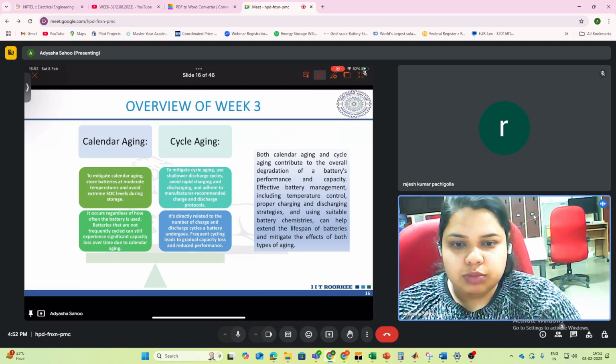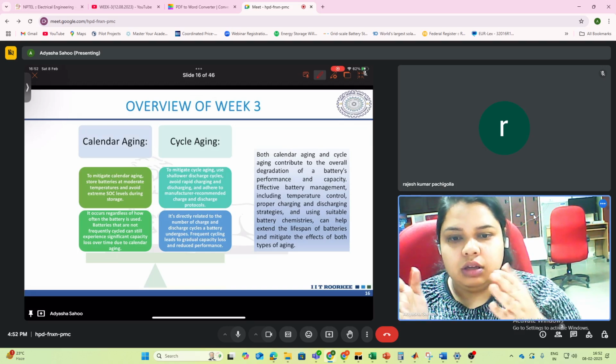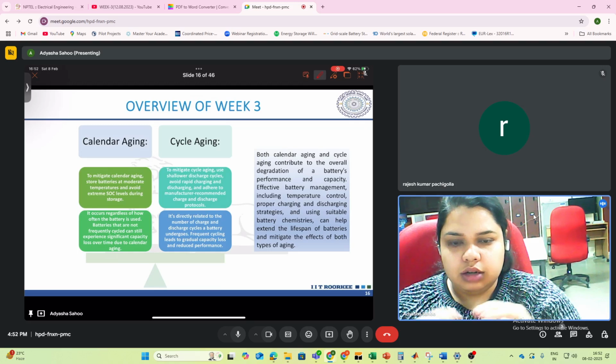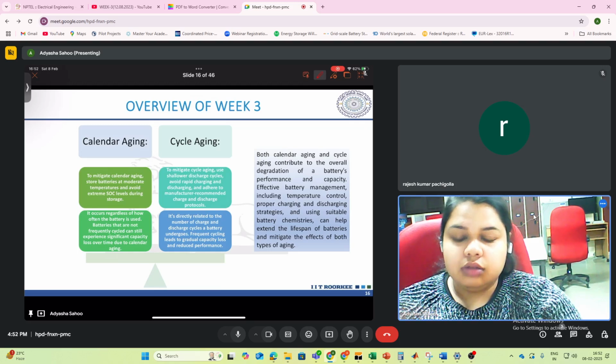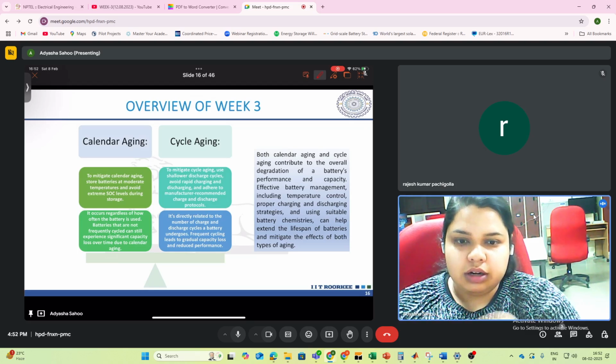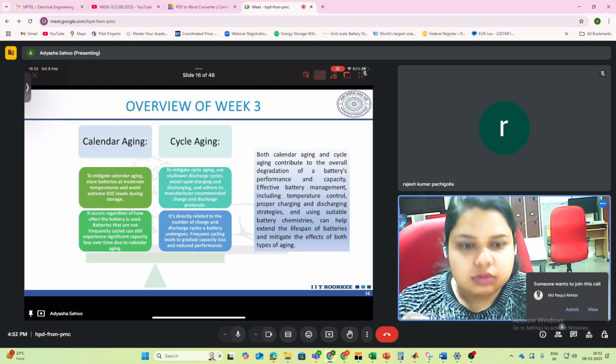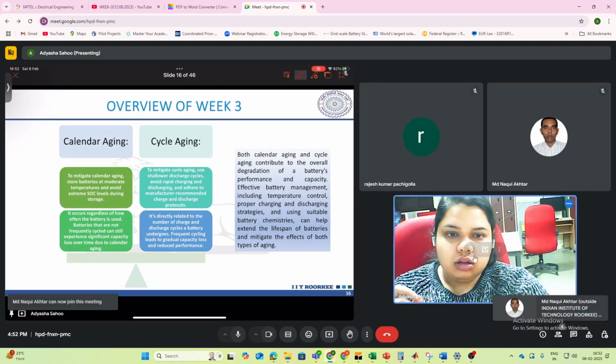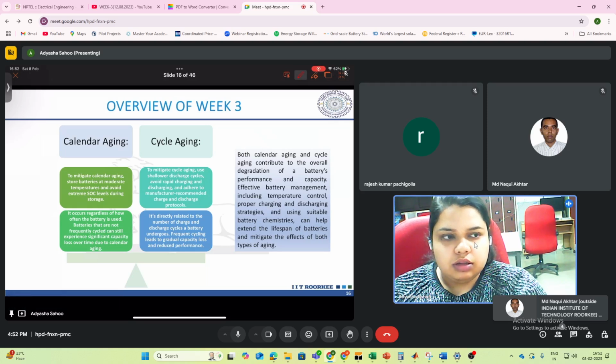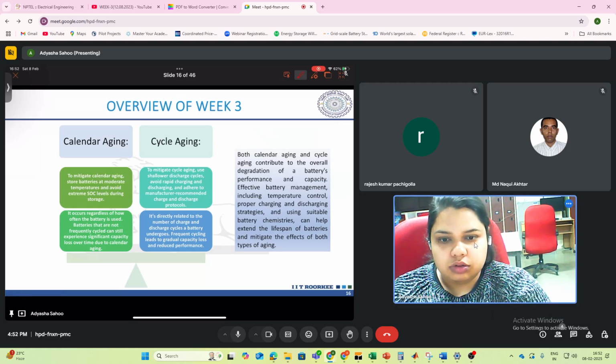And this arrangement will be in racks. They will be arranged in rows and columns, and there will be a structure. And then they will be kept inside a big container. And that container will have other things such as the battery management system. Then there will be the power converters, maybe also inside that container. Power converters, battery management system, the batteries. There may also be a monitor to continuously monitor the health of the battery.